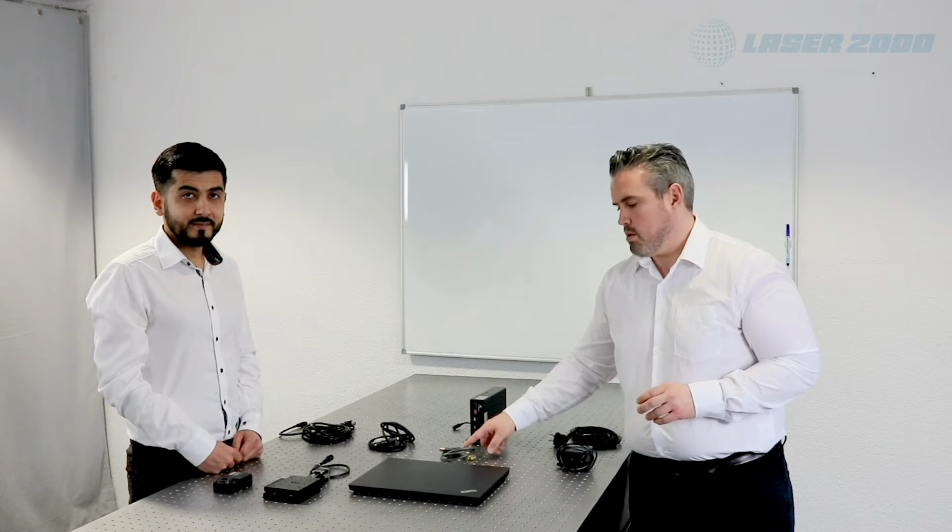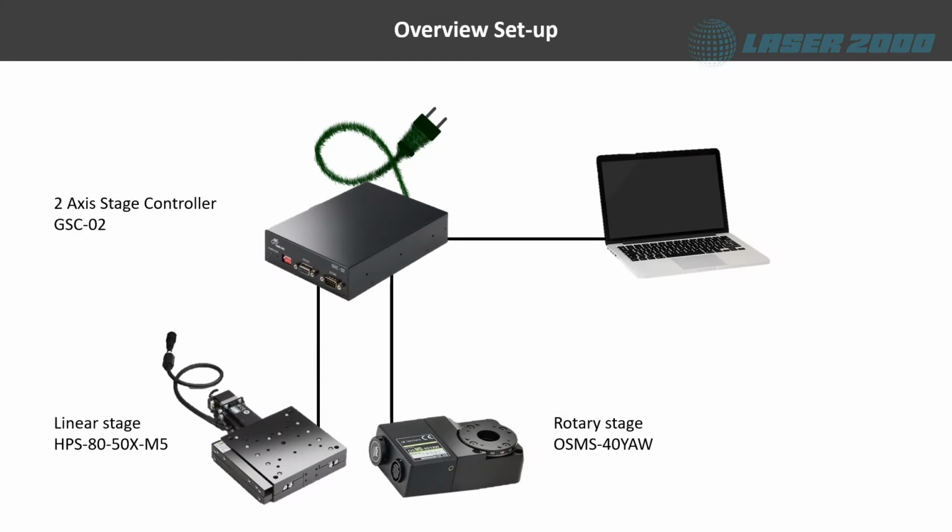And here is an RS232 cable to USB. So we will attach the controller to the computer so we can run the controller via the computer. After connecting the controller with the power supply and the PC, it is important to check the presettings. A too high current may harm our motorized stages. And now Axel will show us the wiring of the controller.